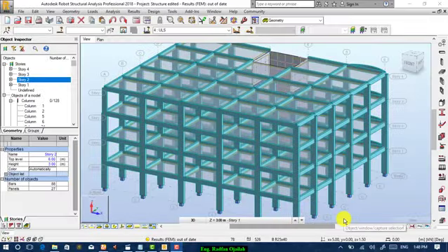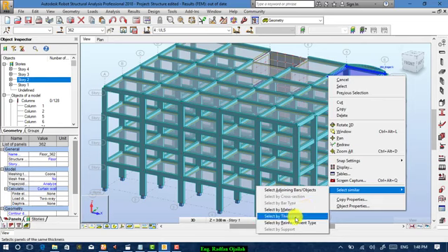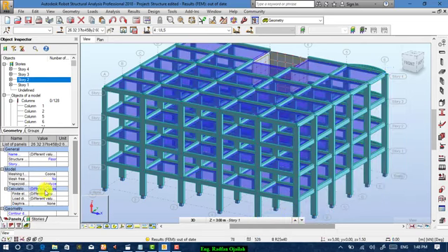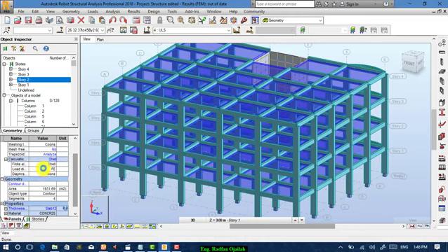For the analysis of slabs, we will not get any results since we didn't use the finite elements method. Then we have to convert them to finite element method. Then select one slab and select Similar by thickness. Then go to Calculation from the Geometry box, and from here change it to Shell, and then do the calculations again.